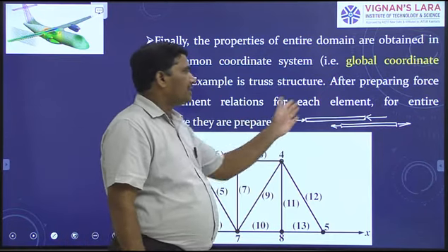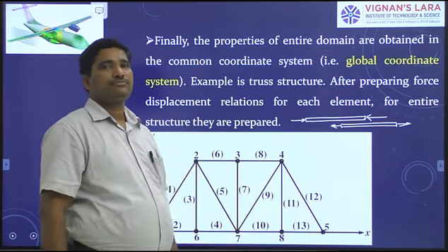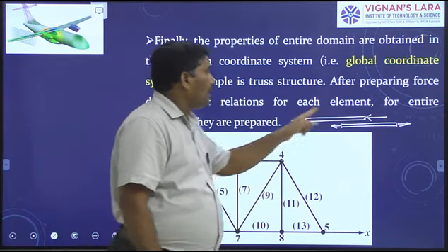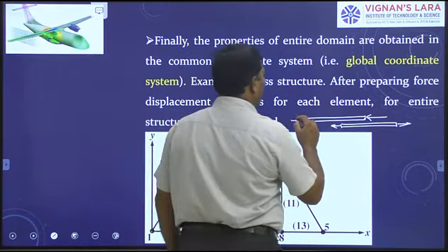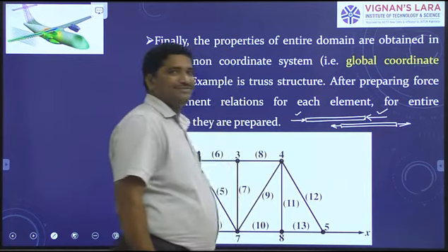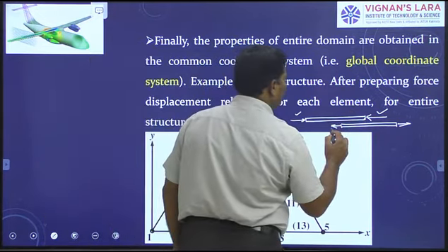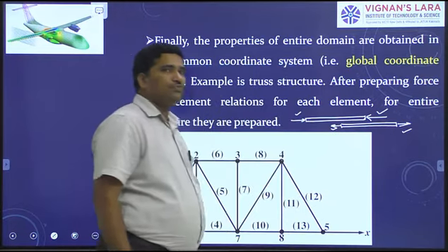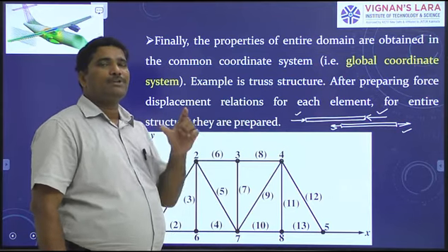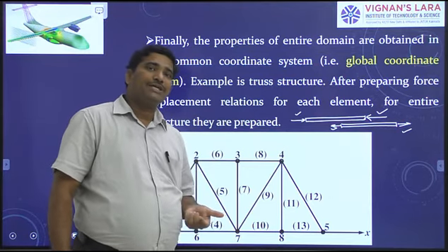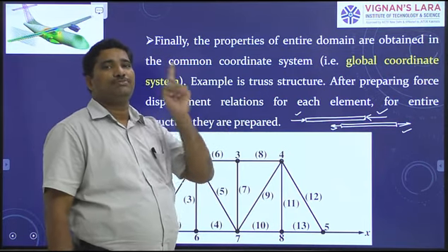Whether the forces are compressive or tensile, their magnitudes are equal, and they are collinear. Both forces have the same line of action. Understand? Whether they are compressive forces or tensile forces, both forces are collinear in action. In a truss member, either compression takes place or tension takes place. A truss member is a two-force member.